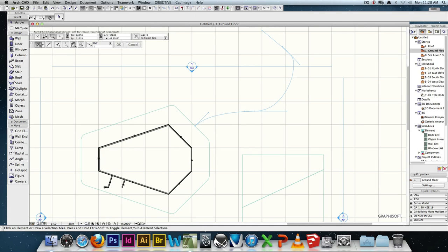So here's my funky path. Well, it's not that funky, really, is it? Because currently it's a straight line, and paths generally aren't just straight lines. In fact, paths are quite complicated because the outside edge is going to have totally different radiuses to the inside edge. If you go around a corner, the inside edge might be radius 1500, the outside edge radius 3000. Now, splines don't have radiuses because they're not arcs or circles. So somehow we have to convert this spline into arcs and circles that somebody could actually draw.